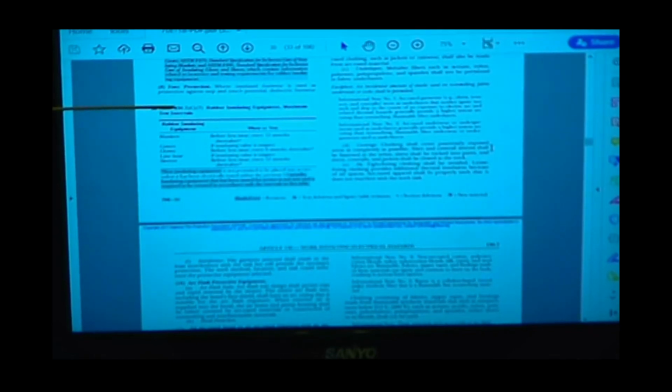Now, right here is your testing for the rubber insulating equipment. Electrical blankets should be tested every 12 months. Electrically rated gloves should be electrically tested every 6 months. The daily air test is once a day. But every 6 months they need to be sent to a laboratory for electrical testing. Some people might even have their equipment there on their sites.